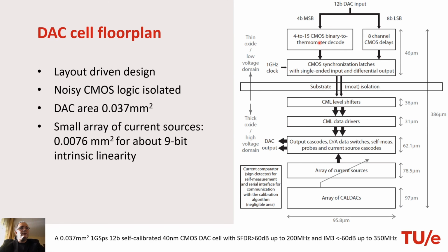Here the switching is very active, CMOS switching, generating a lot of disturbance, while in the analog part we keep everything quiet and clean. For digital gates we use CML logic, for which only constant current is consumed, and we don't have switching of current in the power supply.